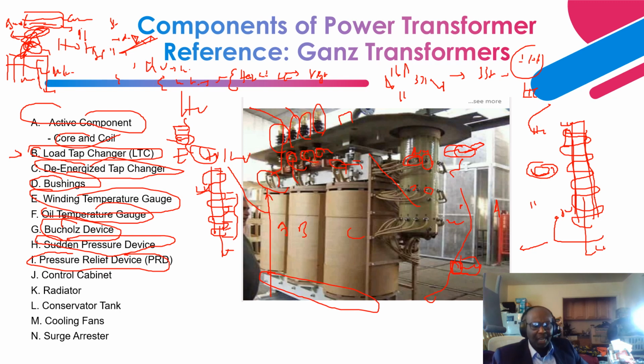So by then the fault current would have grown and basically evolved into a huge electrodynamic force, right? And a huge pressure inside the transformer, right? There has to be a way of basically bringing this pressure out, other than the main tank exploding, right?